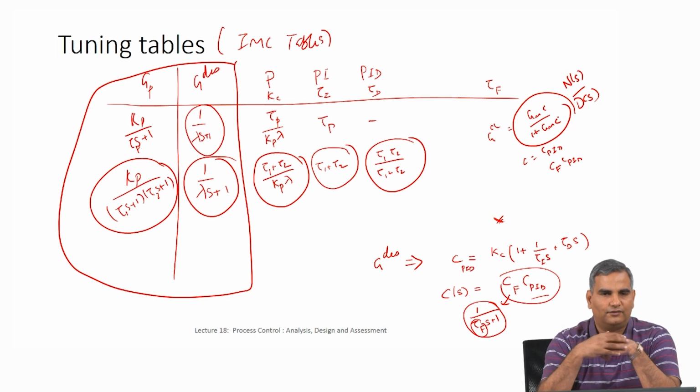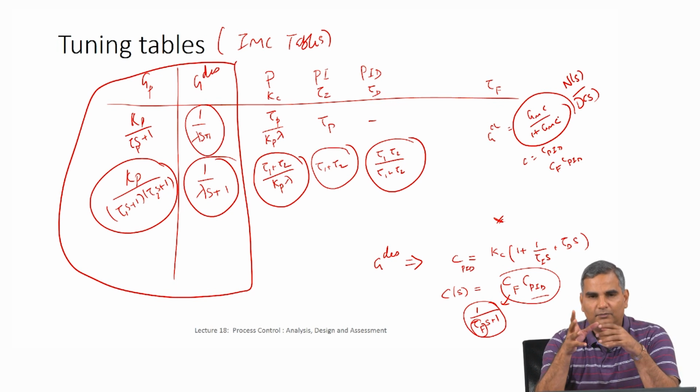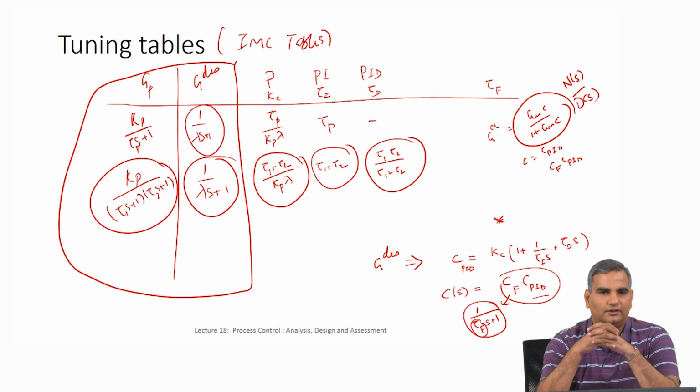So to further verify it, what you do is you construct this table, and if the first column of the table has all positive numbers, then we are guaranteed that there are no roots in the RHP. Again, the beauty is we are not actually computing the roots at any time. However, if there are some negative numbers, depending on the number of sign changes, you can figure out how many roots are in the RHP. So the number of roots in the RHP is equal to the number of sign changes that you see in the first column. Okay, so this is the Routh table.